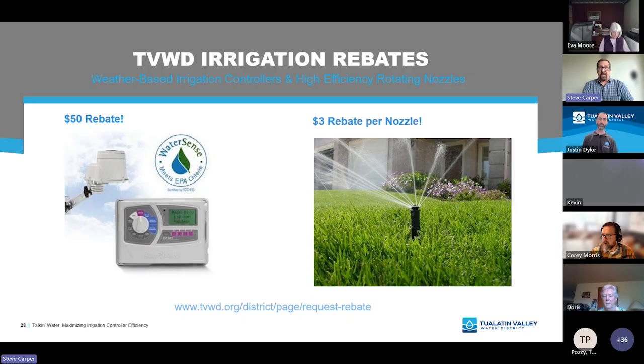So particularly if you're going to have concrete contractors, not that I've ever had any bad experiences with concrete contractors as a landscaper, you just want to get that stuff out of the way. But then also keep in mind after you extend the patio, what's your vision for the landscape? Do you want to have a sprinkler head really close to that to water any plant material that you might be doing along that border? So first, get it out of the way so any construction work is not going to damage the PVC or the funny pipe. Don't just bury it and hope for the best is kind of what I'm getting at.